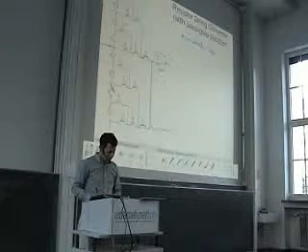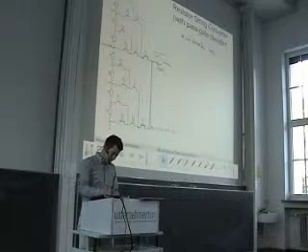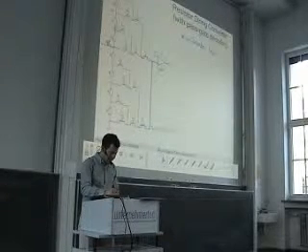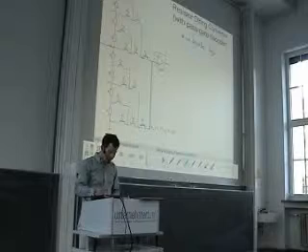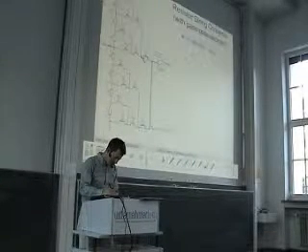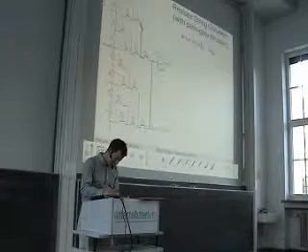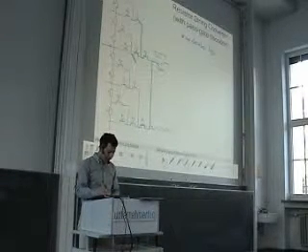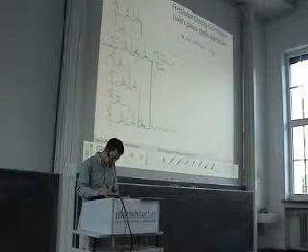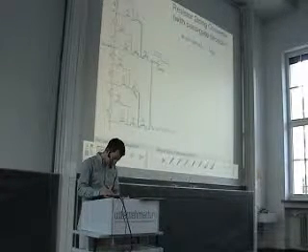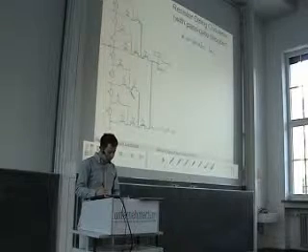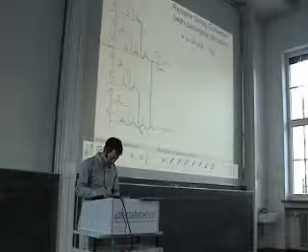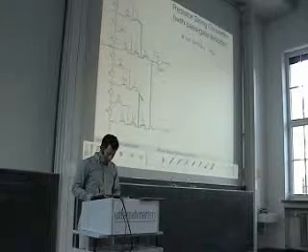is subdivided here. So we subdivide either the lower part into subparts or the higher part into subparts, and we use the second bit in order to select either the higher subpart or the lower subpart. Or if the MSB has selected the lower part, then we use the MSB to use this part or this part, not the MSB, the second significant bit.